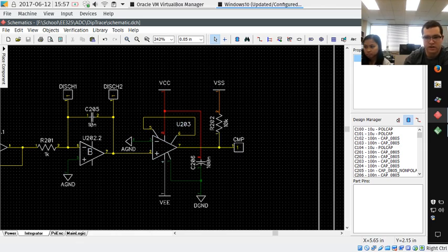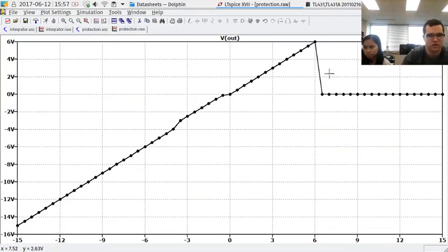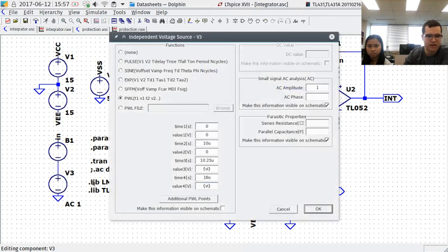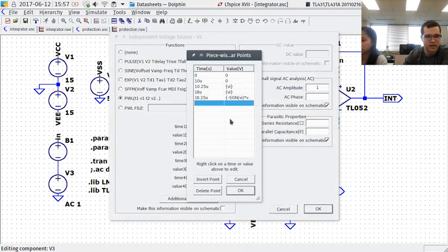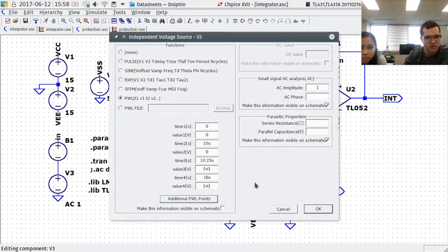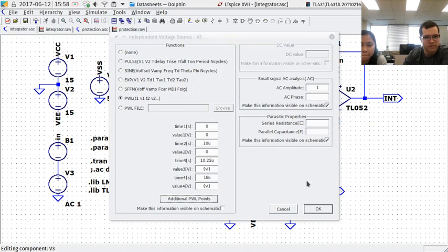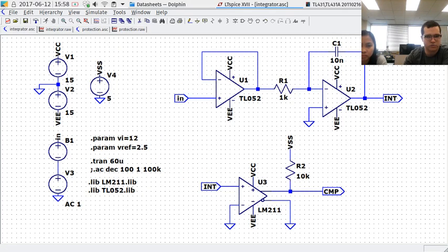Okay. And yes, we did simulate this as well. The switch we couldn't simulate because it's a mixed signal IC, but we do have this supply here using PWL data. It's quite long actually, but it basically simulates the digital portion of the circuit. And we also simulated this with noise.